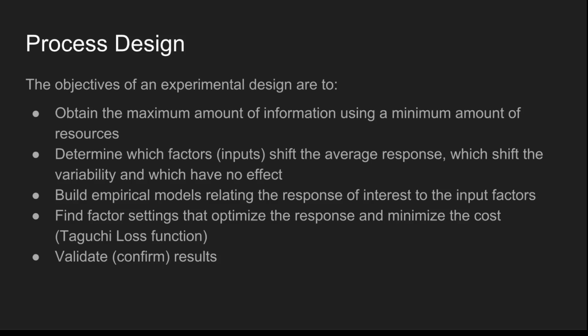The objectives of an experimental design are to obtain the maximum amount of information using a minimum amount of resources, determine which factors shift the average response, which shift the variability and which have no effect, build empirical models relating the response of interest to the input factors, find factor settings that optimize the response and minimize the cost, and validate or confirm results. Taguchi designs use orthogonal arrays, which estimate the effects of factors on the response mean and variation. An orthogonal array means the design is balanced so that factor levels are weighted equally.